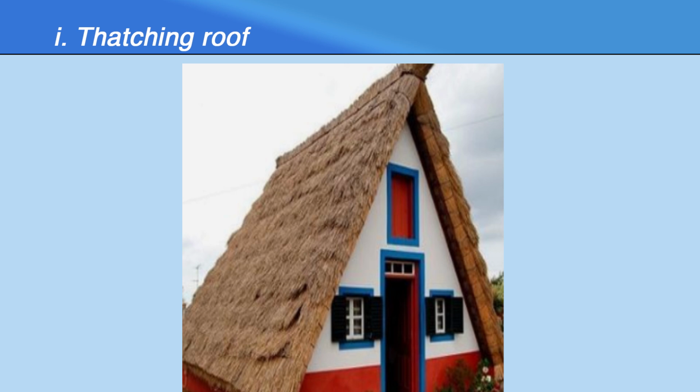The framework to support the thatch consists of round bamboo rafters spaced 20 to 30 cm apart, tied with split bamboo laid at right angles to the rafters. In order to drain the roof effectively, a minimum slope of 45 degrees is kept. The thickness of thatch roofing should be at least 15 centimeters. Normally the thickness varies from 20 to 30 centimeters.